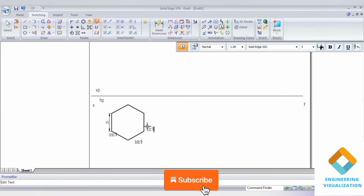So here we need to find out the center of the hexagonal prism. For that at least one or two lines need to be drawn, because since it is a prism, to find out the center of the axis no need to draw all the lines. And here inside of this hexagon we should be drawing the thin lines. No need to draw the thick line, thin line should be drawn here. One or two lines is enough.